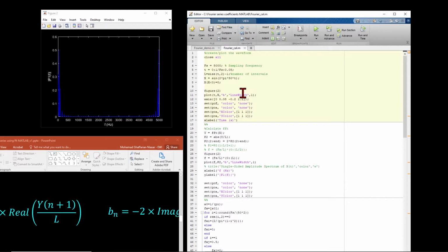According to Nyquist's theorem, the sampling frequency should be at least 2 times the highest frequency. So with 5000, the maximum frequency that we can get theoretically is 2500 Hertz. Actually, in this case, we cannot even get 2500 Hertz because the signal length was limited. So we observe that the signal is mirrored against this center frequency, and from this center frequency onward, this information is not useful. We have to discard them.